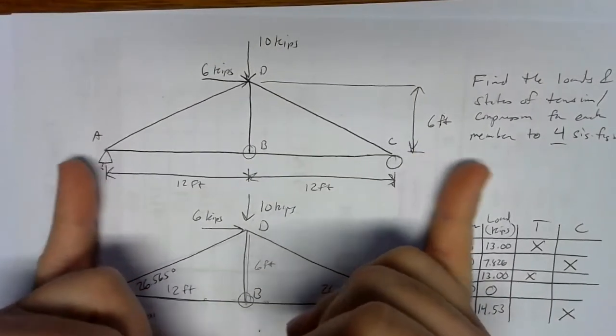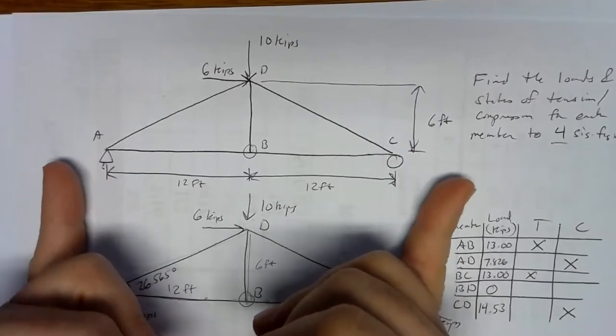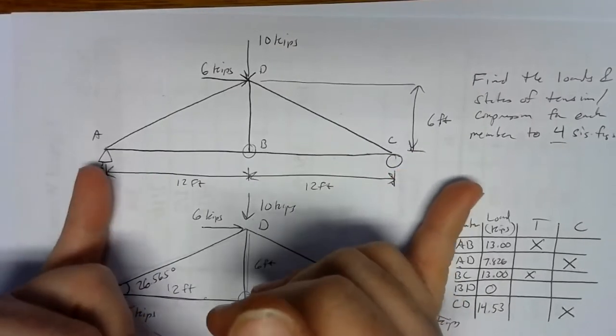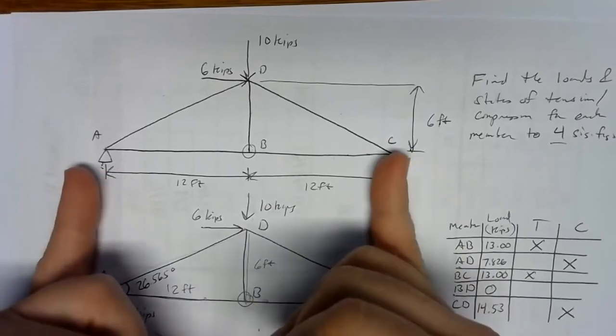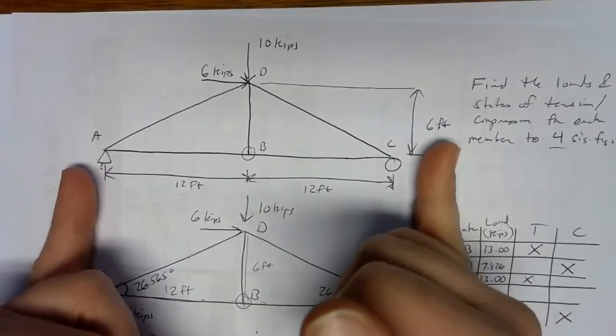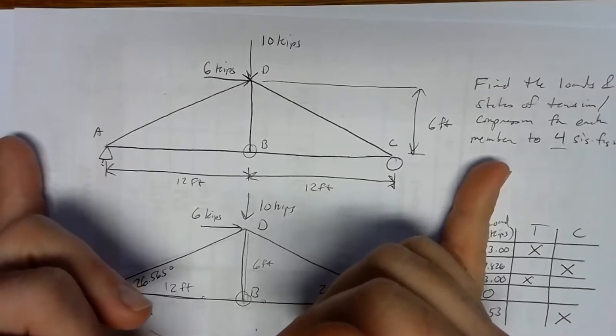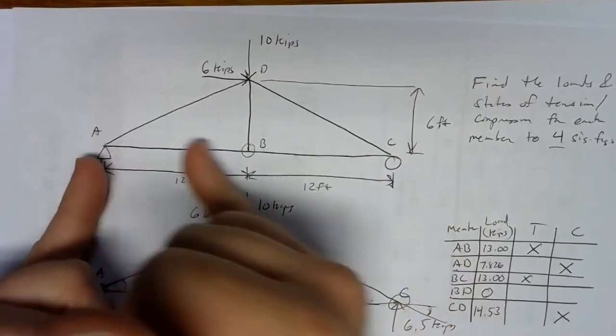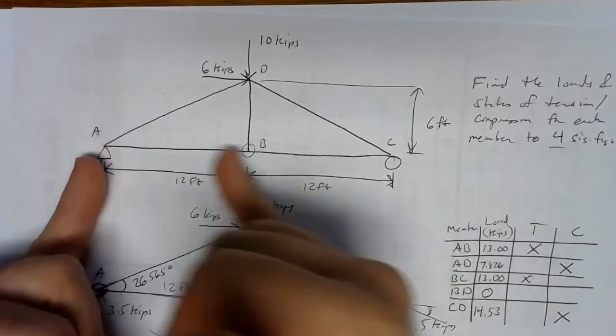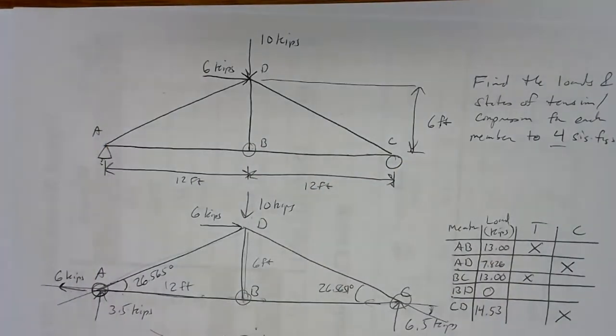And my father, who used to do some building inspection on the side, told me once, if I was ever looking at a house that involved a cathedral ceiling, take a big level, put it against the walls on the outside, and make sure those walls aren't being pushed apart. So it's that bottom piece, what they call the bottom cord or the ceiling joist, that is holding those walls together. So those are usually in tension.